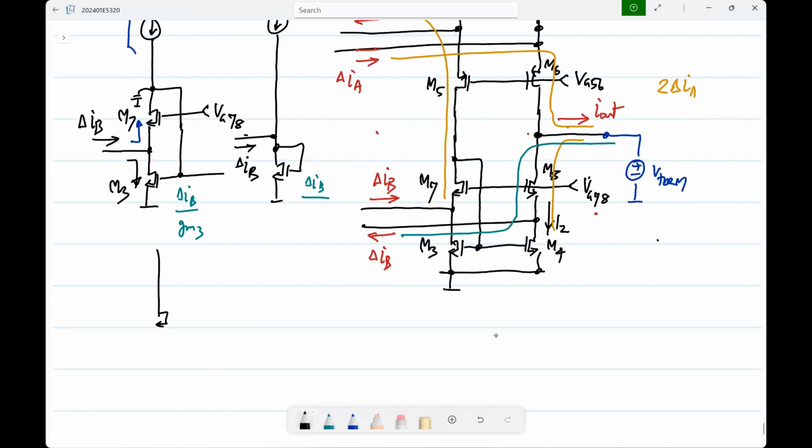So when you see something like this, yes, the impedance is 1 by gm. You are almost trained to automatically say this. But this is true only if, now let's introduce some impedance here, RD. If you evaluate it along with this rds, you will get some expression that also includes RD. When RD is somewhat small, then it doesn't matter. This will be very close to 1 by gm. But very clearly, when RD is infinity, this cannot give you 1 by gm, right? Because no incremental current can flow there. It's an open circuit. So that is something you may have to be careful about in some cases.